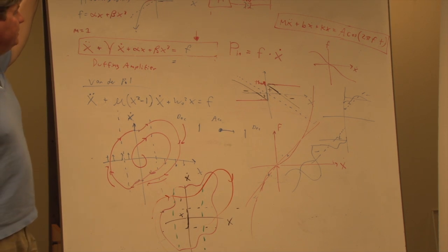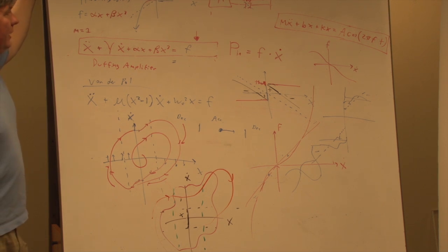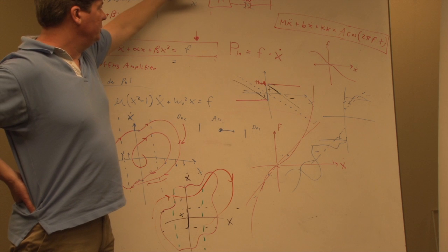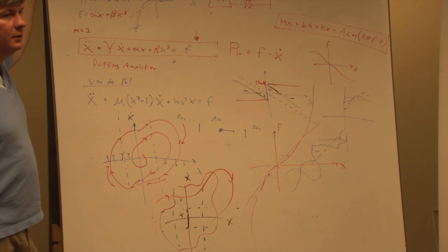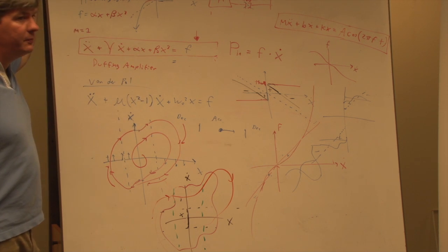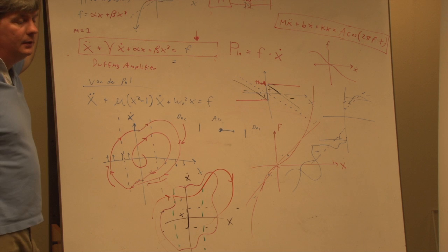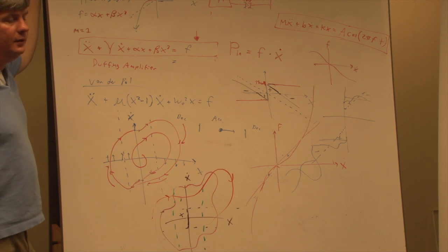Right, no, in FastRunner we want to make them all be physical elements so that you get the energetics for free. So actually you don't want damping, you want some kind of energy storage. Well, there's going to be damping no matter what. If there's not damping in your joints, there will be damping from wind resistance, and that's a square damping. But you don't want to add in damping unless it's already there. Virtual damping by withholding effort is okay, just don't drive it as hard as though the wind were blowing. But he's saying don't add physical dampers because that would destroy your energetics. Right, we don't want to add physical dampers unless necessary to get stability, but wherever we can avoid it.